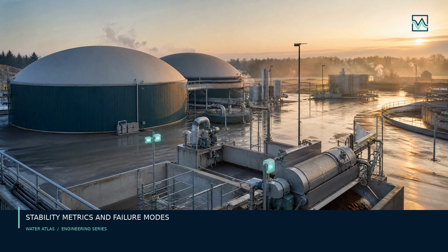Implementing advanced anaerobic digestion and resource recovery is never a one-size-fits-all proposition. Project managers and consulting engineers must evaluate a rigorous site-specific decision framework. Capital expenditure for digestion and thermal pretreatment facilities is substantial, requiring thorough techno-economic analysis to balance upfront investment against long-term energy savings, tipping fee revenues from co-digestion of high-strength organic wastes, and reduced biosolids hauling costs. Key decision factors include plant capacity, influent solids characteristics, local energy tariffs, and regional biosolids disposal regulations.